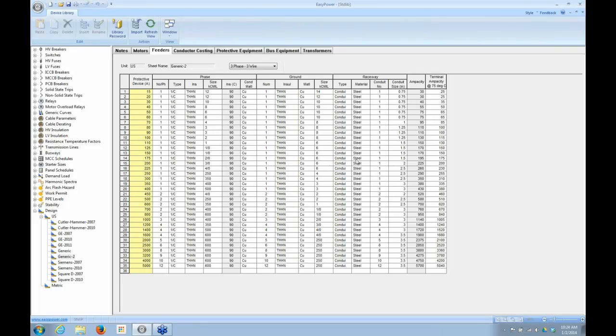It's going to default to steel conduit, 1 conduit, 1.5 inch, with this ampacity at 75 degrees C, 175 amps. So basically it's going to go up the table until it finds the right size and then insert this size into the AutoDesign. So it's actually fairly straightforward. If you have a 4-wire circuit, then there's a different table. Okay. So the only thing it's going to affect is the neutral and the conduit size.